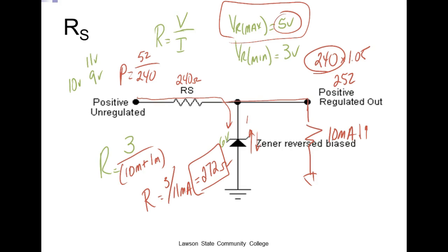So we use a quarter watt resistor right there. Quarter watt is 250 milliwatts. That would be fine. That's double, right? So now we not only know what size resistor to stick in there, we also know to make sure we buy the right wattage resistor.